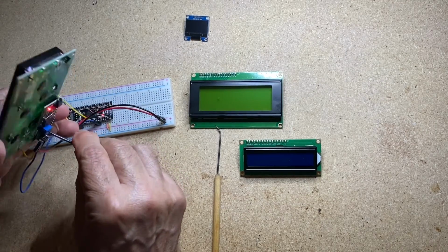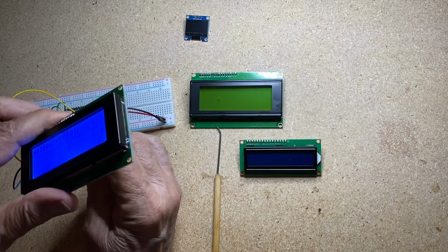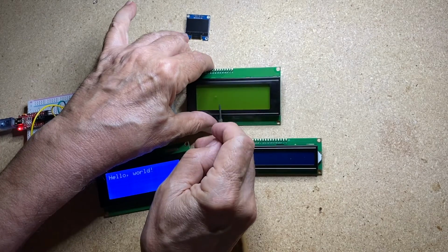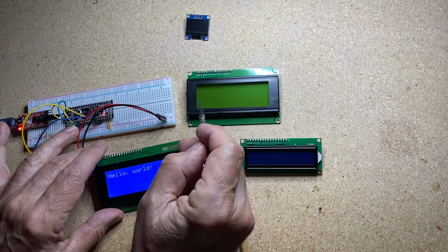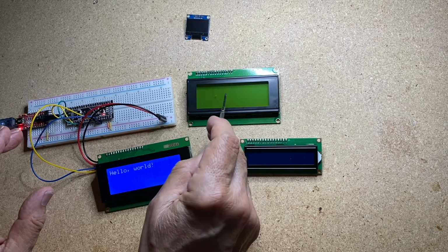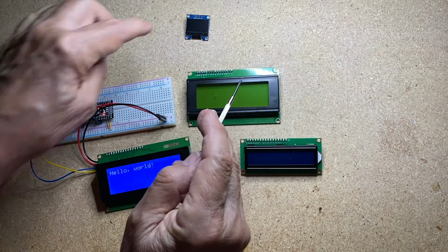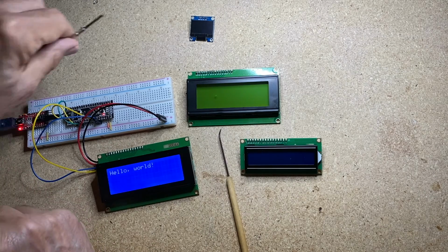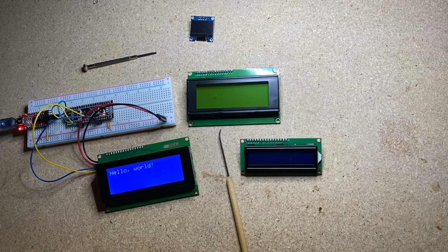The interesting thing that I was originally going to show you with this display is that it turned out I had a little speck on the glass, and it turned out that this one has a different address than this one. So you really need to use an I2C scanner to see what the address is of the display that you're going to be using. Of course, this has a different address, and this has a different address, and this has a different address. Some addresses are set as default and you can override them, but these, I think, are all fixed addresses, and you need to know what they are, and the only way you can do that is really to run an I2C scanner just to see what devices you have on your I2C bus.